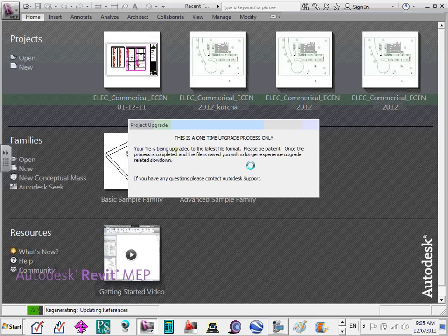It always dumps it into your documents, always. The local file is defaulted to my documents. It hides it there, like a scratch pad, correct? The local file is more or less a scratch pad for you to work on, load your stuff. And if all hell breaks loose and you lose the central, what we did last time, we take your local and we create a central file from your local. It did happen. I don't want this to happen, but it comes in handy too.